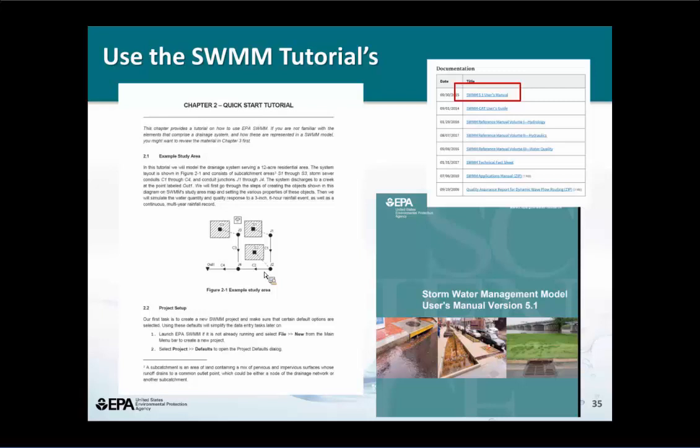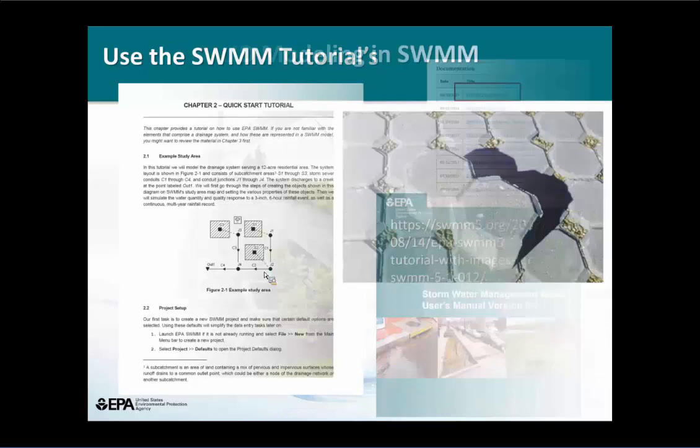Some of my colleagues here in Cincinnati who are starting with SWMM, I recommend they start with just looking. SWMM can do a lot of things. I would recommend you start with the sub-catchment, the junction, the conduit, the outfall, and then work your way up to some of the more elaborate things that SWMM can handle. Here is a web page where Bob Dickinson from Innovyze has a click-by-click, screen-by-screen, nothing-left-to-the-imagination tutorial demonstration of the SWMM user's manual tutorial. If you get stuck, you can go there.